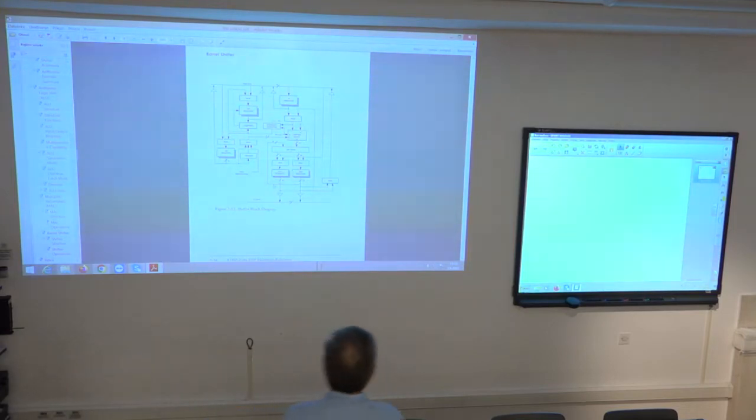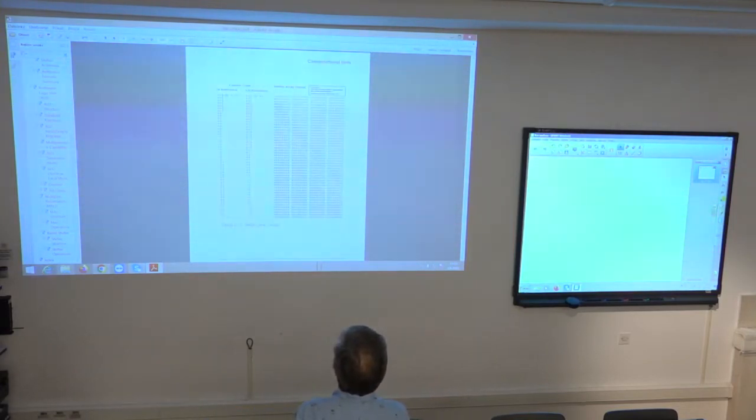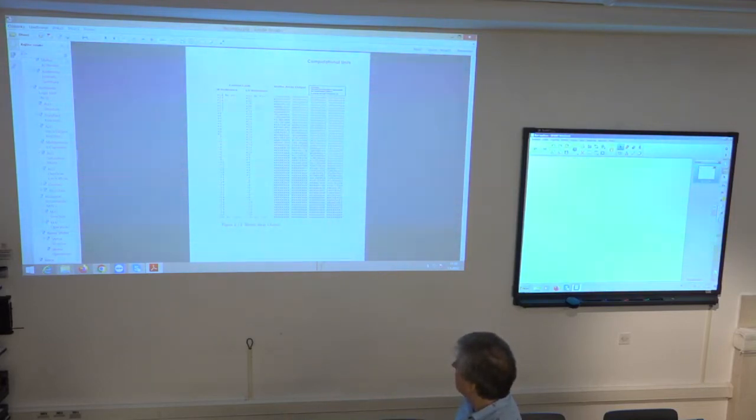You have here several examples what happens for arithmetic shift, for logical shift, and it describes two cases. When you have high reference, shift left or right relative to the upper word, or shift left or right relative to the low. In this case, the input value was ABC and so on, and then this value is shifted to each possible position in the output register based on the input value that is either in this SE register or as a constant in the instruction.